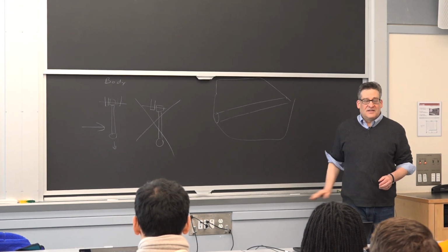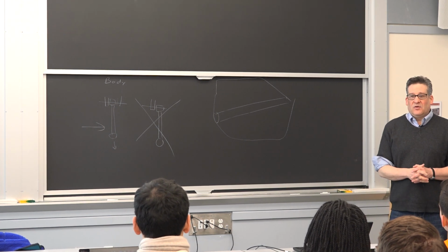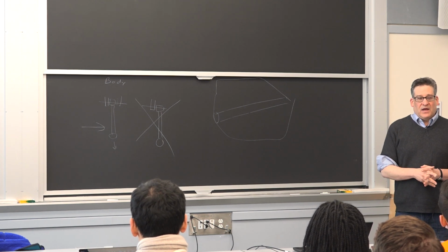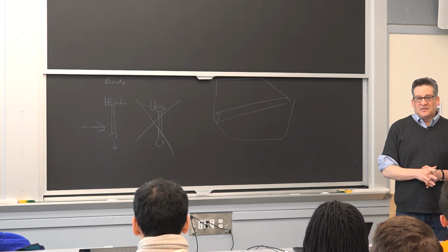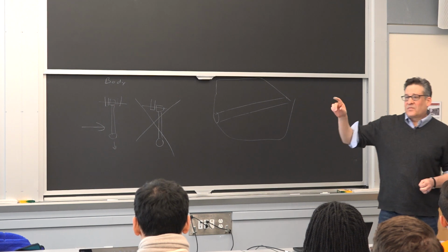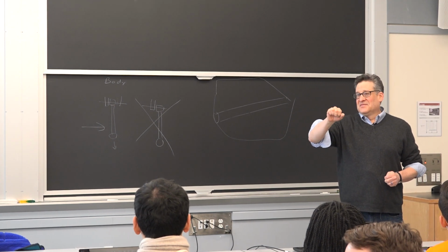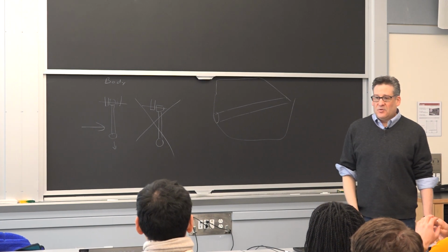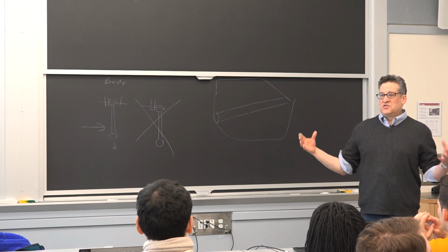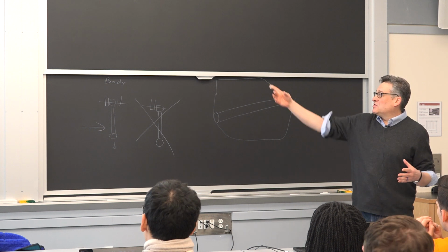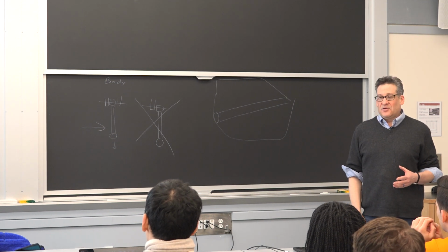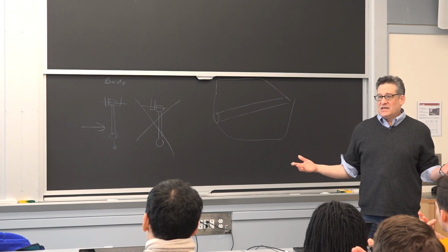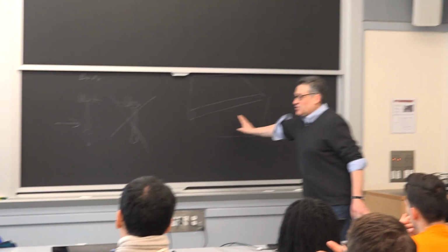Okay, and the side intrusion beam is typically made of steel, and the reason they make that part of steel, not aluminum, is because they're packaging limited, right? I'm sorry, what was your name again? Kimberly. Like Kim was pointing out, you're packaging limited here. You can't always make these tubes bigger, right? There's a certain point where these tubes get so big that you can't move the wheel, or your legs can't go past the frame. It's the same thing here. Inside a door, you're very limited.